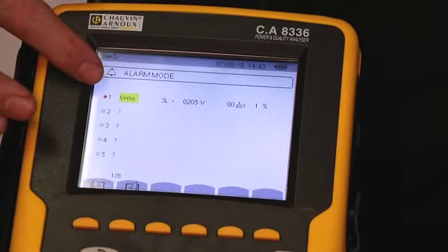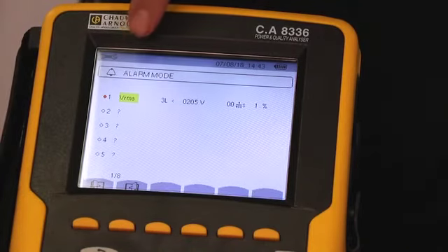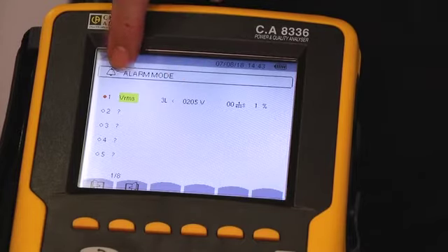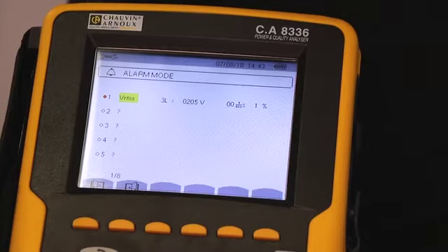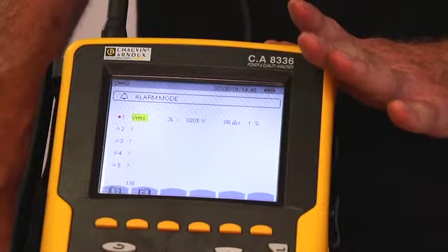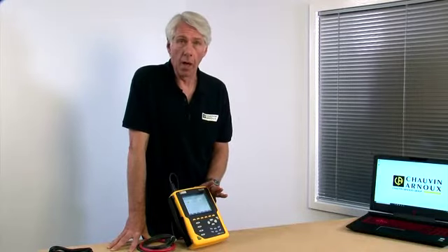At the top of page 1, I can select whatever voltage, current, etc. I want the alarms to be applied to. For example, either volts RMS or amps RMS. I can also set up alarms on frequency. Now I'm going to leave this set to all 3 voltage phases, and I'll set an alarm to trigger if any of those voltages drops to less than 205 volts. I hit enter to store the alarm setting. As well as setting the voltage threshold, it is possible to set a threshold for duration too, right down to 1/100th of a second, therefore deciding how sensitive the alarm will be.